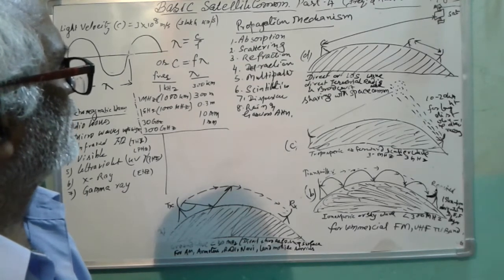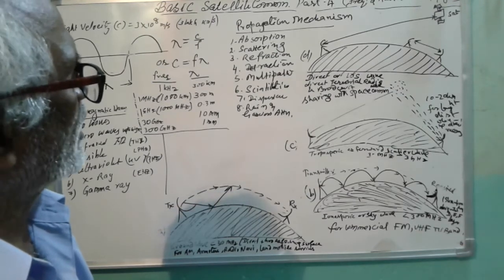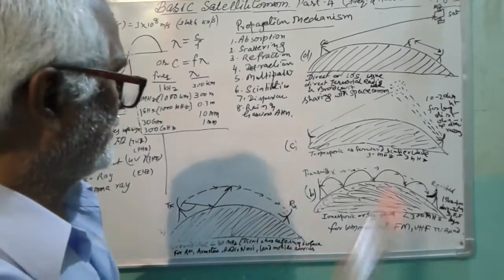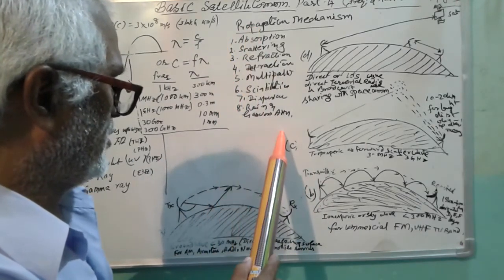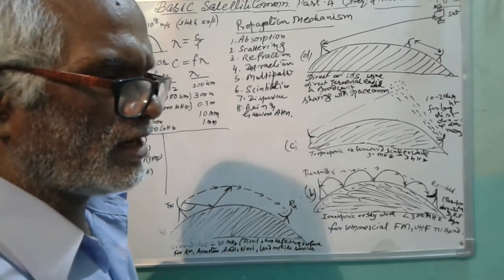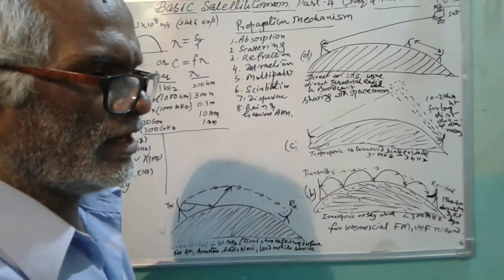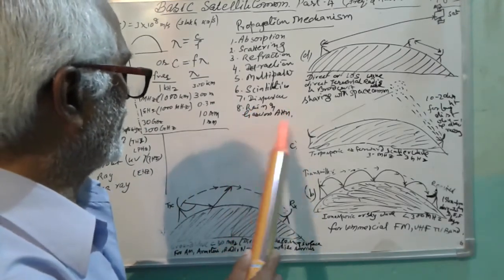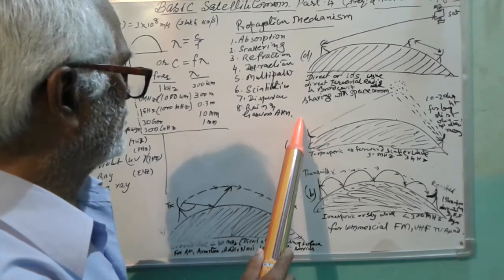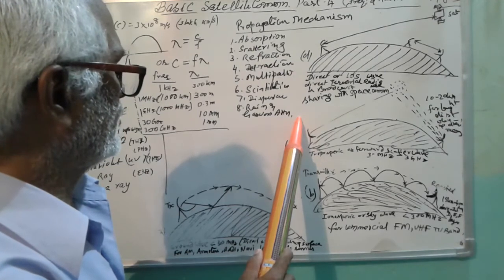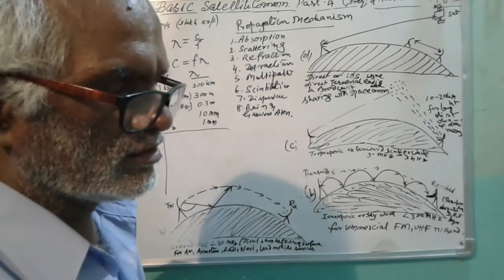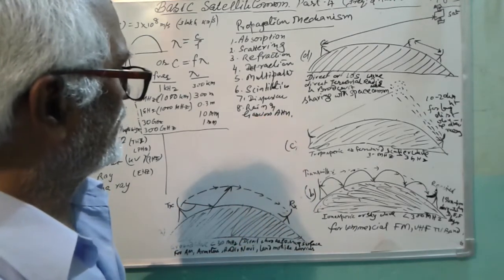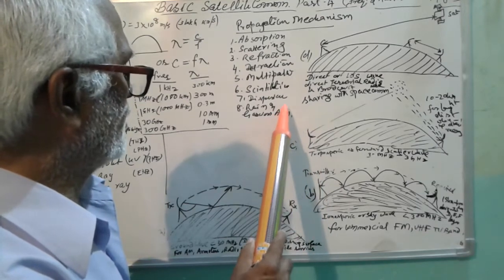And so many mechanisms or methods are adopted to come out from this, because due to these propagation phenomena, the frequency, bandwidth, amplitude, polarization, and the angles of arrival will get disturbed. And for rain and gaseous attenuation above 10 gigahertz to higher frequency, the attenuation of the signal and the polarization will be affected.